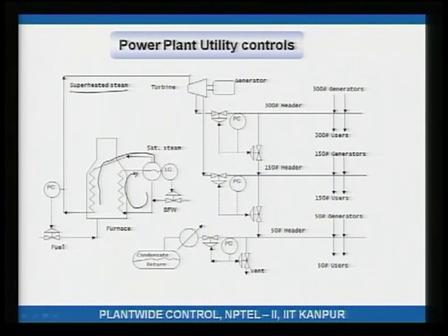So, it is sent to a turbine to generate electricity. From a very high pressure you go to a pressure of about 300 psi. How much is a psi? 15. So, 300 divided by 15 is how much? About 20 bars, 20, 21, 22 kilograms per centimeter square. So, this is about 20 kgs or 20 atmospheres of that order.